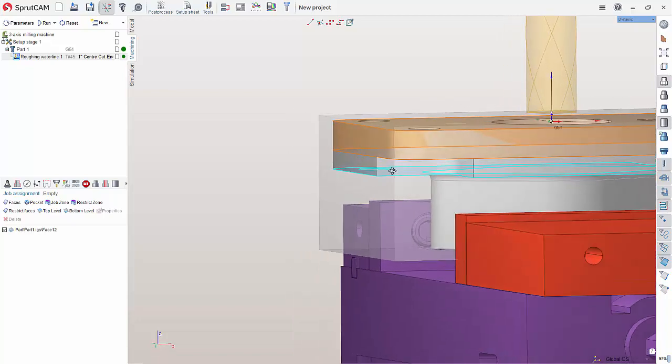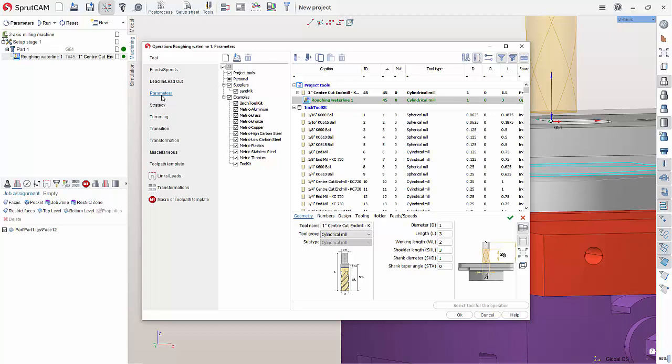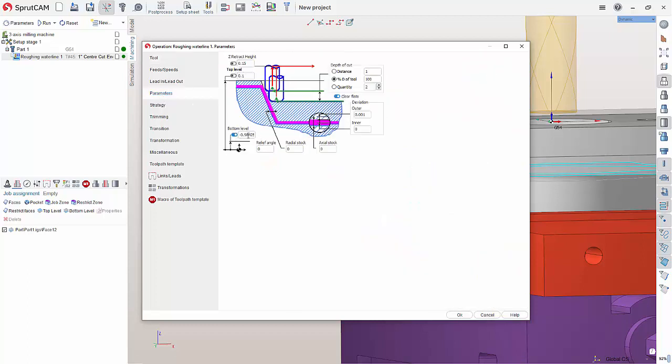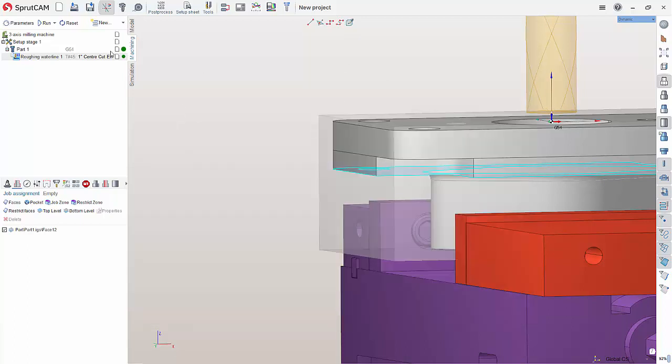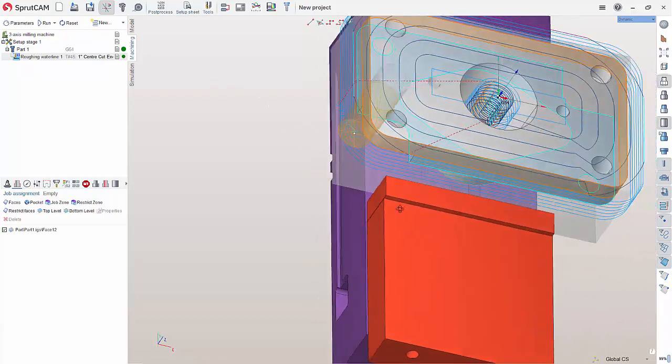And then what I want to do is actually go in there and modify that just a little bit so it just goes past it. And that's just to break that off. So I'm going to do -1 inch. And I'll add a few passes onto that just to go, hit run. And you'll see it go in there.